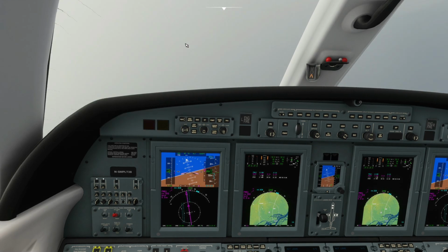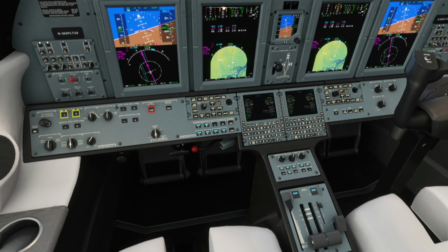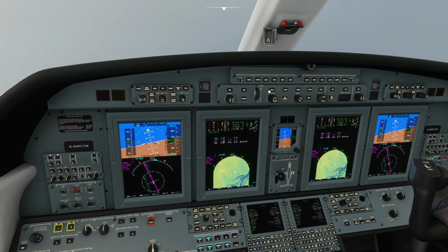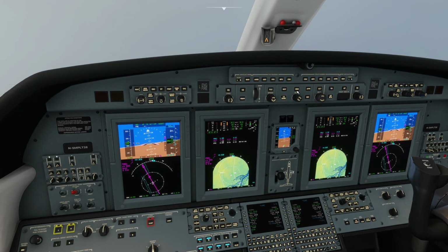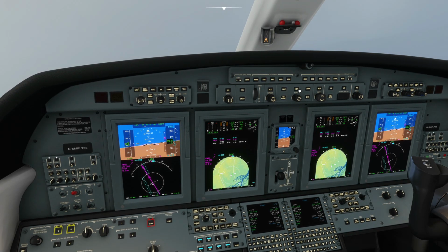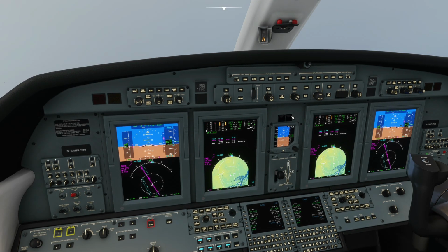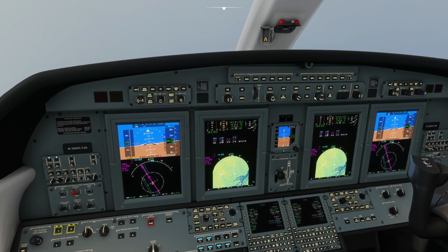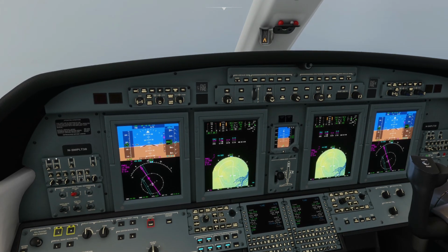Okay, goodbye. We will tune out of that frequency and we will not worry about ATC. I'm not sure why vertical navigation or navigation mode is gone. That's interesting. LNAV looks like it's not working, so I'm switching to heading mode. And we need to descend to 4,000. Let's do that first.